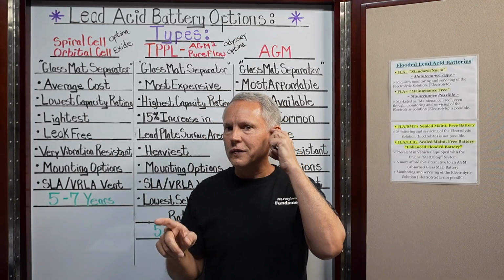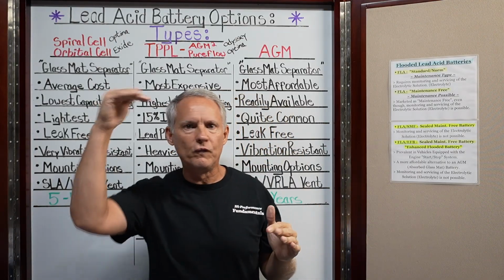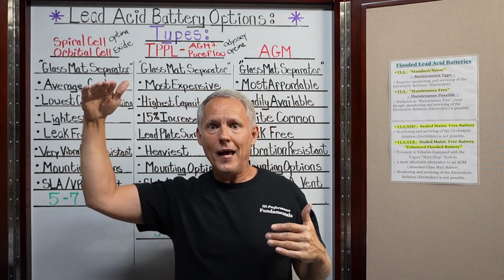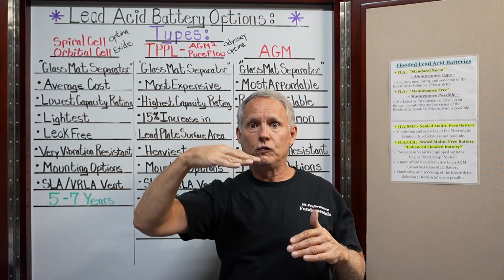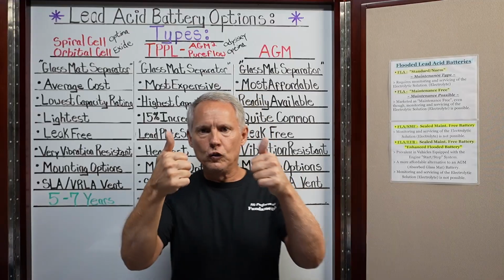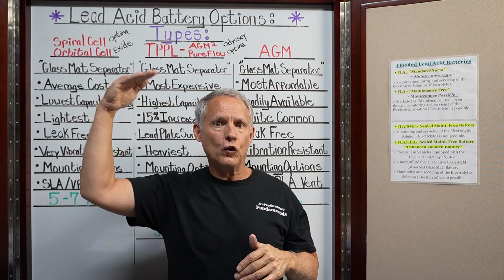Now, when you move into a 16 volt battery, you've got to be a little more careful, because the same scenario occurs with the voltage drop and a voltage sag. You go from, let's say, 16.8 or 17 volts fully charged, and it might drop down to 15 volts while cranking, or 14.5 or whatever. But that battery may require a charging voltage of 18 volts or greater.